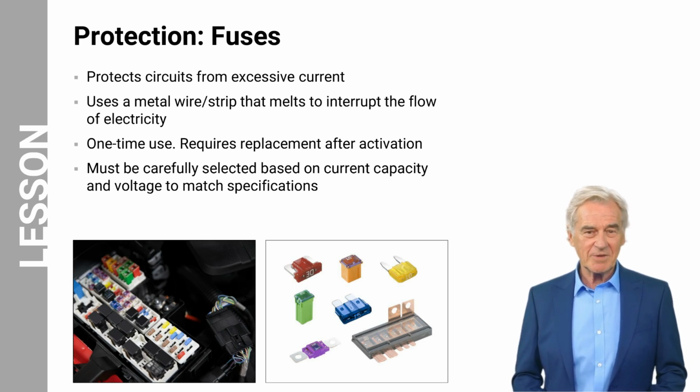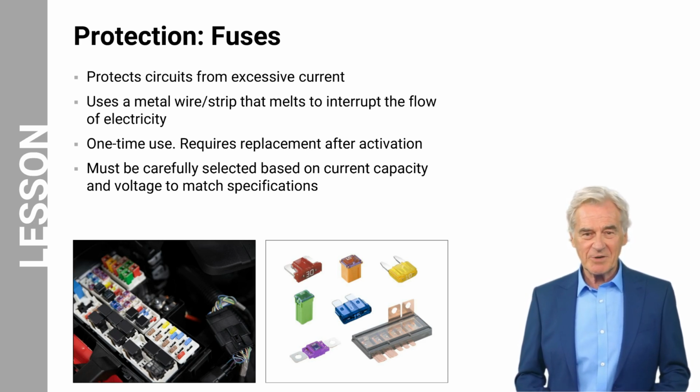Fuses play an important role in safeguarding automotive electrical systems from excessive current, protecting the circuit. Employing a metal wire or a strip that melts when exposed to elevated currents, fuses are designed to interrupt the flow of electricity and prevent damage to vehicle wiring and components. Once a fuse is activated due to overcurrent, it becomes a one-time use device and requires replacement to restore circuit